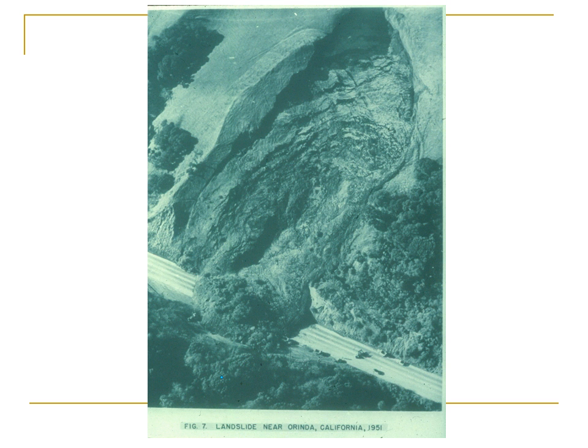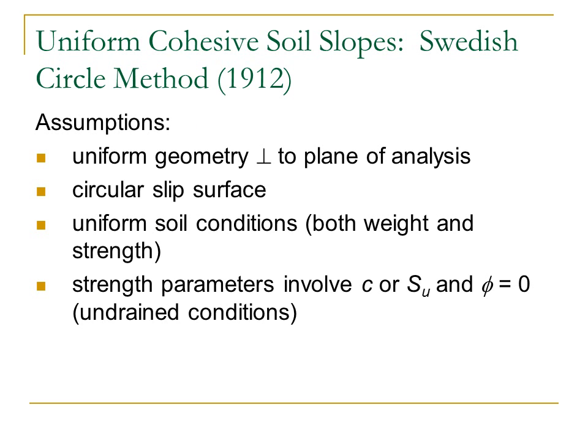There are other kinds of slides that don't involve sliding on a plane. This is a rotational type failure, so we need an appropriate rotational based stability analysis. And for that, we look at a number of methods that originated with the Swedish circle method. The Swedish circle method is over 100 years old, and a number of assumptions that are in it we can't normally make, but it's still sometimes useful to use the Swedish circle method, and I'll show you a modern example in a few minutes.